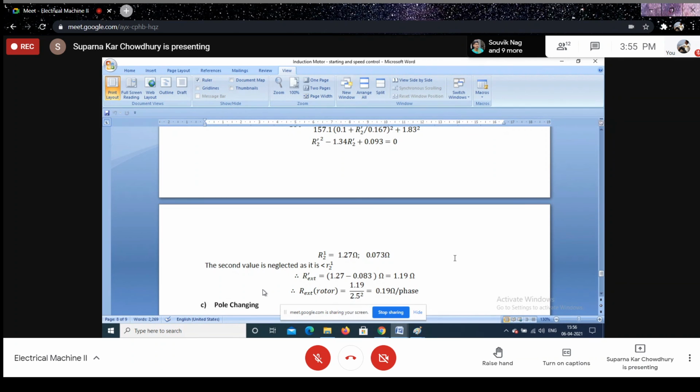But the main advantage of the DC motor was that its speed control was very effective, very easy, and very inexpensive. So initially in the industry, Ward Leonard systems with DC motors were mainly used, but nowadays we have very reliable power electronic devices. With power electronic circuitry, we can control the speed of the induction motor very accurately, so DC machines are being replaced by induction motors.